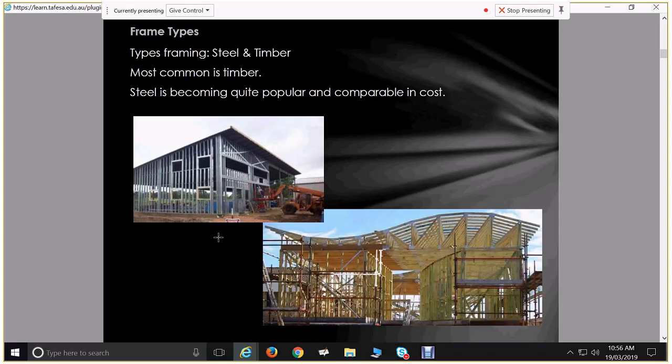Look, your failure in timber structures typically happens at all your joints. It's about your fixings and how your joints are constructed. And so for that matter, I'd say essentially a steel frame will perform better in both of those scenarios because they have much stronger joints. Those joints are engineered and they're controlled, and there's a lot of homogeneity. All those joints are going to be the same. They're going to be quite reliable.